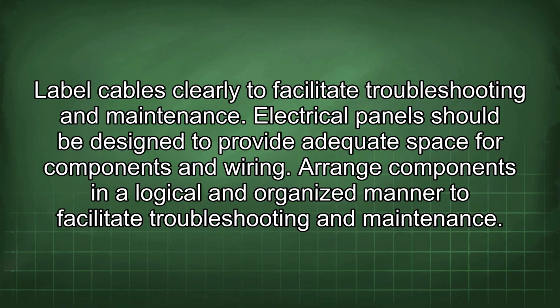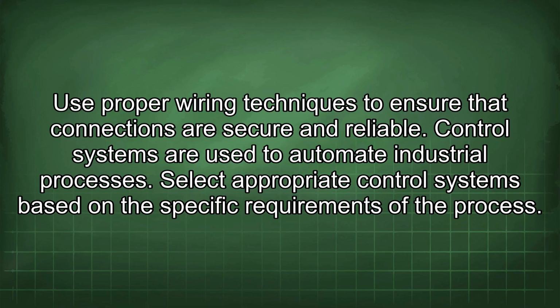The electrical panel should be designed to provide adequate space for components and wiring. Arrange components in a logical and organized manner to facilitate troubleshooting and maintenance. Use proper wiring techniques to ensure that connections are secure and reliable.